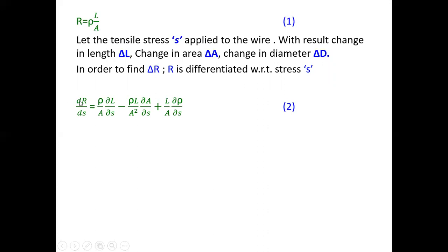dR by dS is equal to rho by A dL by dS, minus rho L divided by A square dA by dS, plus L by A d rho by dS. This is the equation after the stretching.